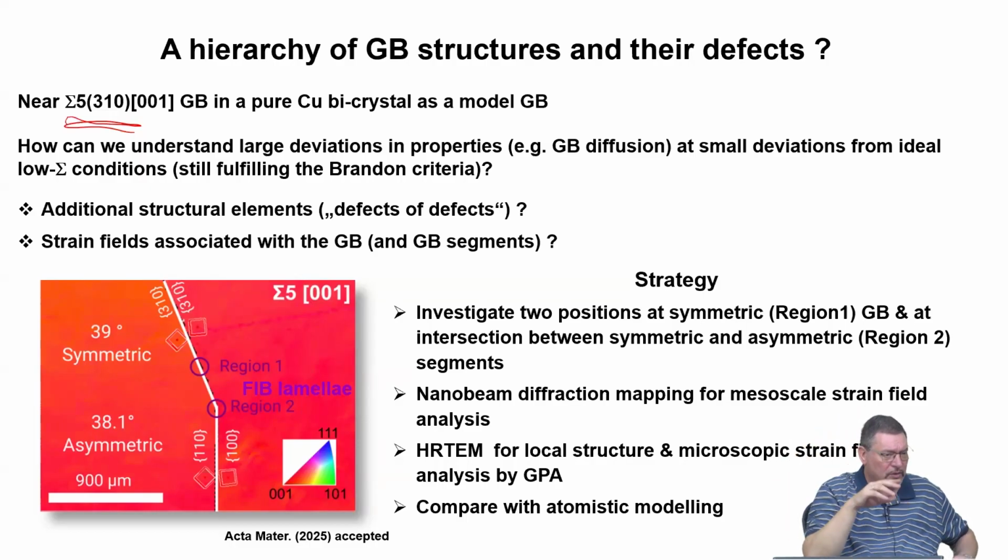Because it's a diffraction signal, it's related to the orientation and the specificities of the crystal lattice that gives you the diffraction of these incoming electrons with the outcoming. And so this is a method of looking at the orientation distribution function of a polycrystalline material. Because you know the orientations of the crystals, you also know the nature of the boundaries, the interfaces between them. And this is normally displayed in color codes, and this is shown here.